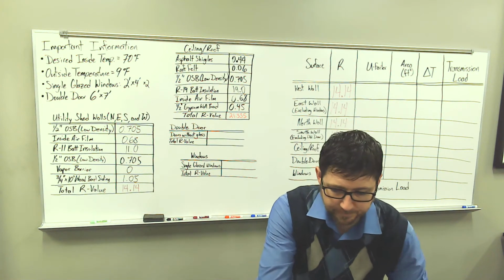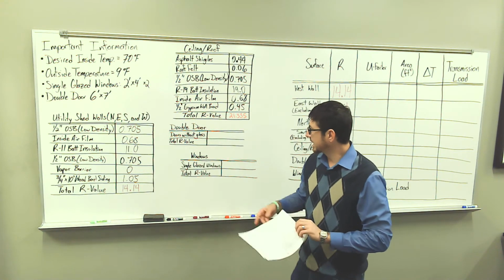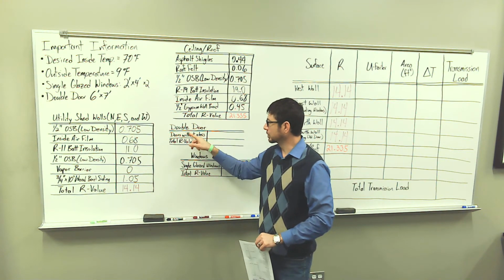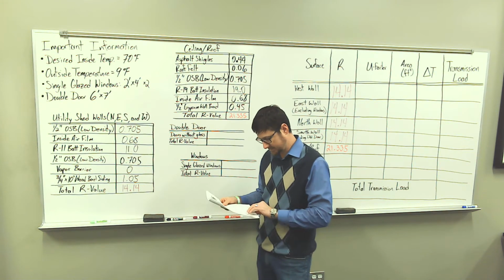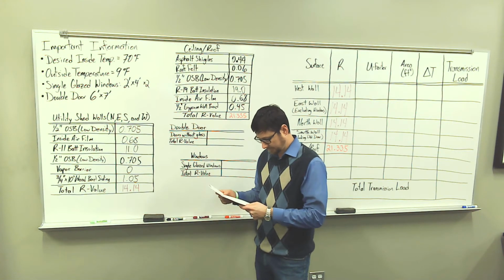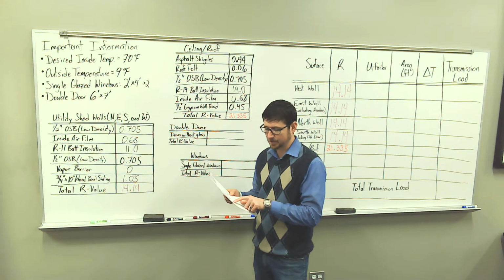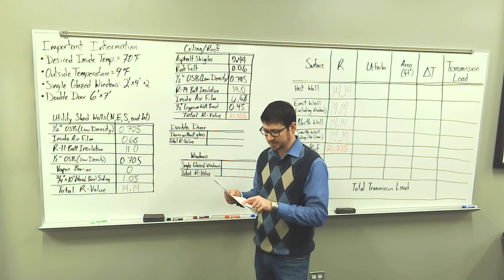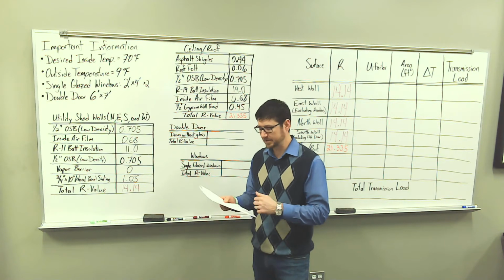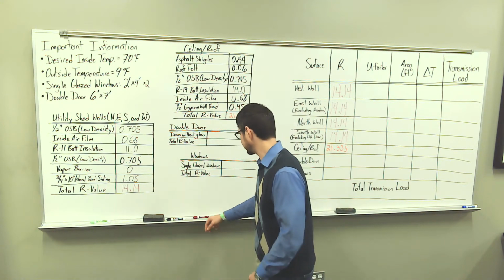Next, let's take a look at the double doors. So what we're going to do, go back to the R value densities chart, and we're looking at the doors without glass. I believe that's on page 2, the back of the first page. So it's under the section Common Rules of Thumb. It says doors without glass in the last row. It is 1.67.